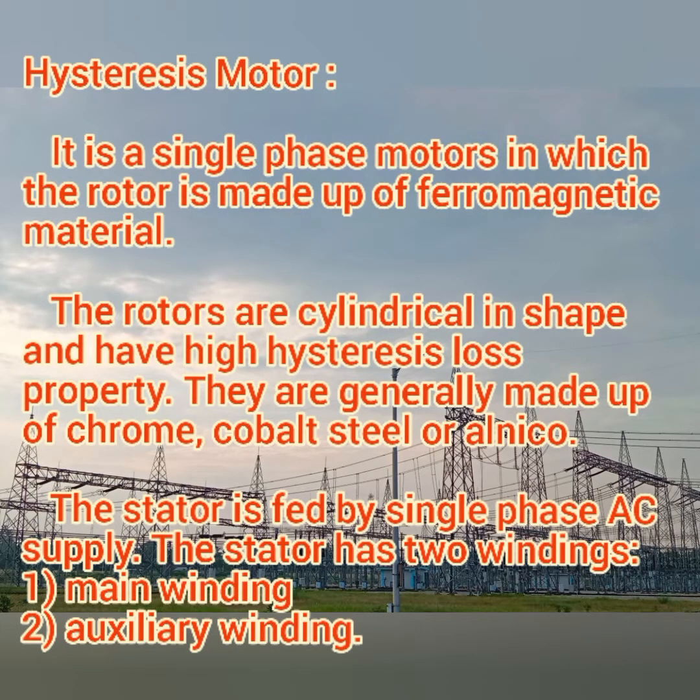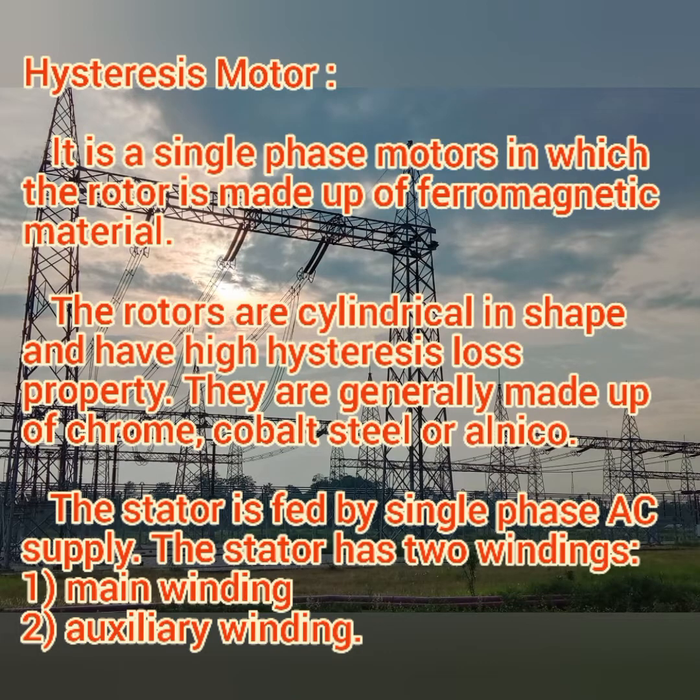Next, coming to the subdivision, the hysteresis motor. The hysteresis motor is a single phase motor in which the rotor is made up of ferromagnetic materials. The rotors are cylindrical in shape and have a high hysteresis loss property. They are generally made of chrome, cobalt steel, or alnico. Then the stator is fed a single phase AC supply.